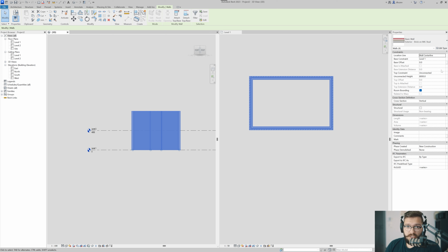Now, to us, this is okay, but if we have a project in which I want to say that my exterior walls go from a certain level to another certain level, I may want to constrain that to something. So I would say a top constraint, put it at Level 2, boom, good to go. Does that mean that I cannot surpass it? Absolutely not. One of the things I can do right away is use top offset. So let's say I give it 1000, or 1 meter.